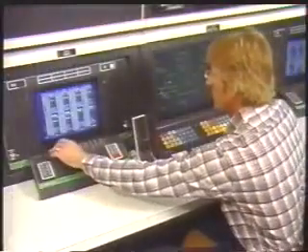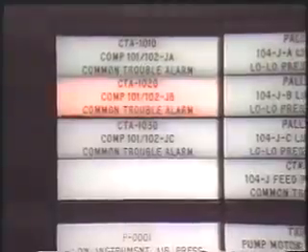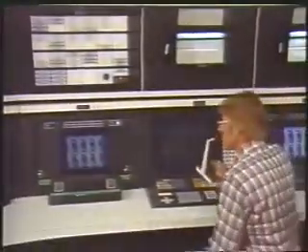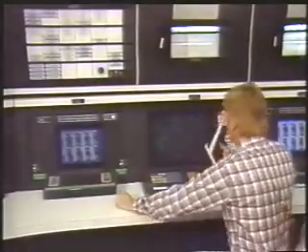Some abnormal situations may call for an emergency furnace shutdown. Under these circumstances, the burner fuel is stopped immediately and the process flow may have to be dumped. You should be familiar with your company's emergency procedures so that you can quickly shut down the furnace in the event of trouble.